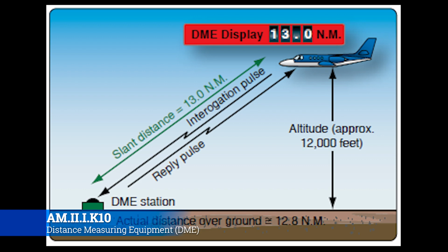Now, that means that one VOR DME station can tell you pretty much exactly where you're at. The DME is really, really accurate, and the VOR also is accurate down to just a few degrees. So if you have those two data points with a high level of fidelity, then you can pretty well know exactly where you are on a sectional.